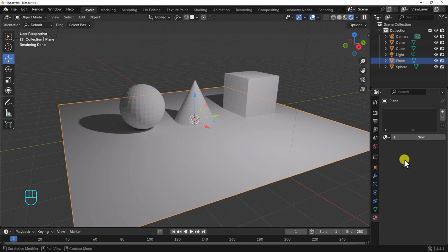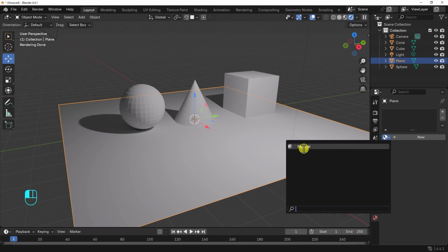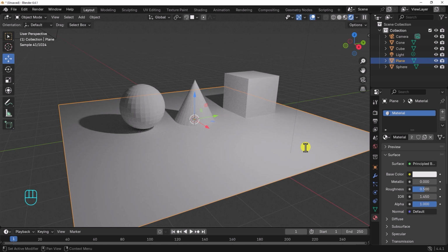In Blender, there is a default material, but it needs to be applied to any new primitives that you add into the scene. If you click on this little materials icon drop down here, you will see the list of materials available in the scene. And here is our default material. With the plane selected, go ahead and click on material in the list. Okay, now not much changed in the viewport, but something has changed in the properties panel for sure.